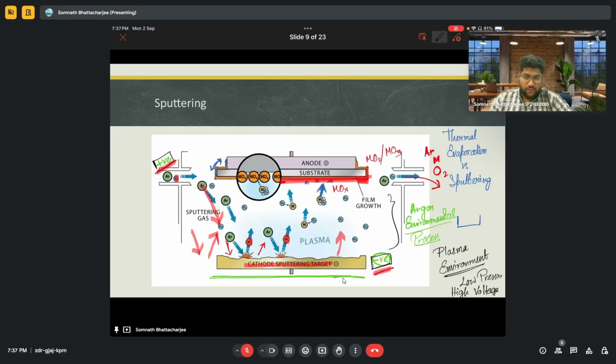And we need low pressure obviously, to increase the velocity of these particles and also the length the particles can move inside a specific pressure. What I was saying is that apart from sputtering and thermal deposition, there are specific CVD techniques where we use APCVD, MOCVD, PECVD, this kind of thing.